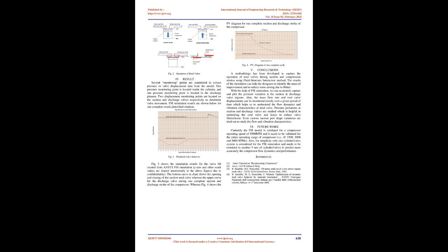Conclusions. A methodology has been developed to capture the operation of reed valves during suction and compression strokes using fluid structure interaction method. The results of the simulation can help the designers to identify the areas of improvement and to reduce noise arising due to flutter. With the help of FSI simulation, we can accurately capture and plot the pressure variation at the suction and discharge valve regions. Also, the mass flow rate and reed valve displacements can be monitored closely over a given period of time, which helps us to understand the flow dynamics and vibration characteristics of reed valve.